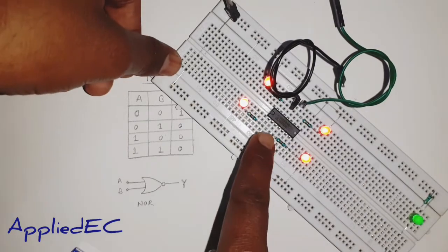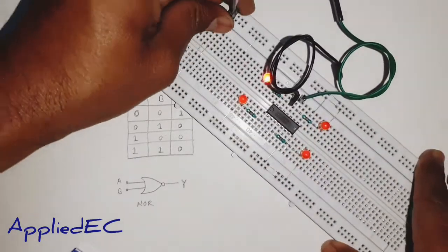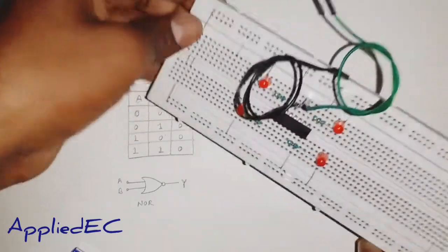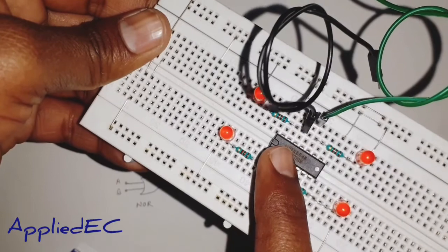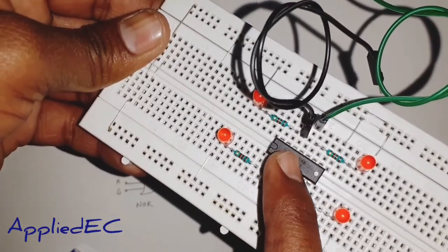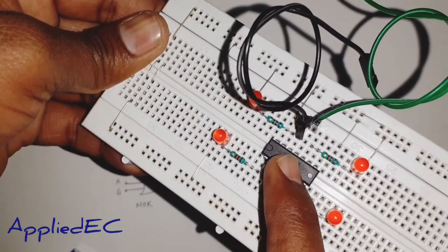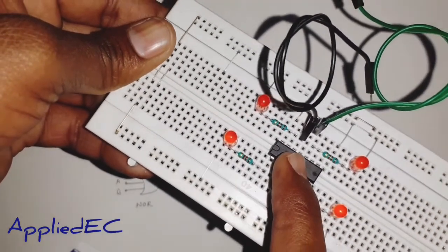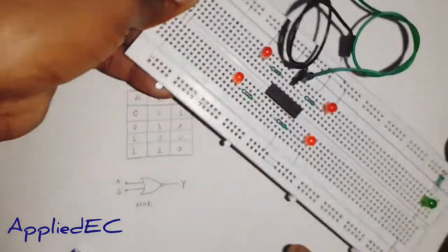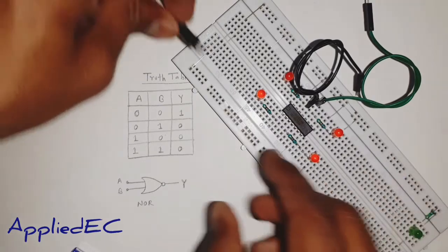So I have connected for this 4th NOR gate. So we remove the power out to show you. Like the pin 15th is the output, and 14 is the A input, and the 13 is the B input here. So these are the 2 inputs, and this is the output of the Y. So this explains here. So now I'm going to connect.